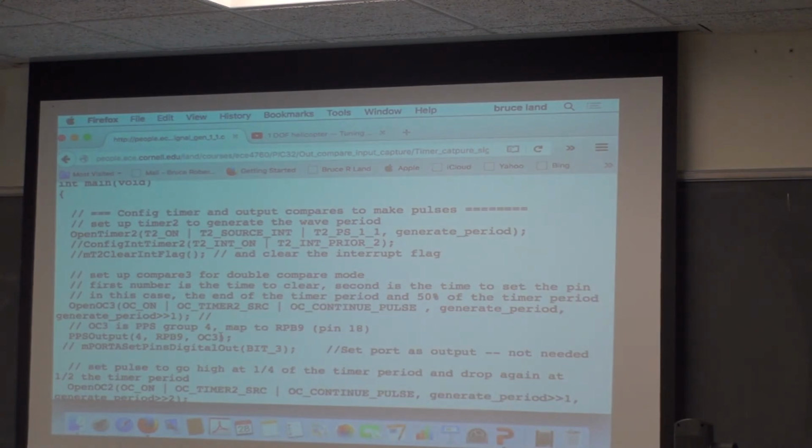Now, what this compiler does is say, Bozo doesn't know what he's talking about, let's do a system reset. So the default behavior is you turn on an interrupt for which there is no interrupt service routine, and the behavior will be reset as fast as possible, forever. So when you say, that's weird, the TFT keeps clearing over and over again, the next thing you think is, what interrupt did I turn on by accident? Don't uncomment that.